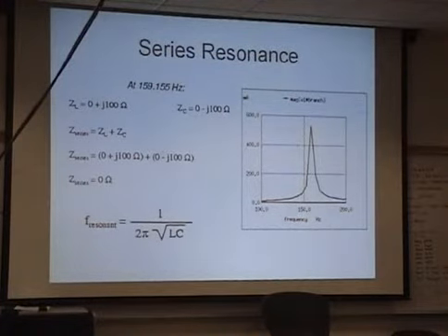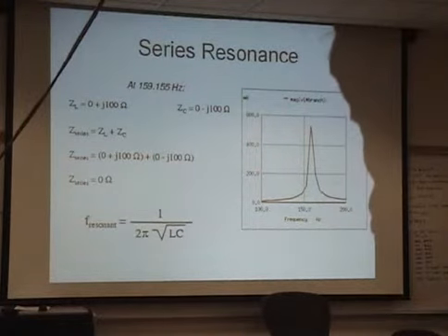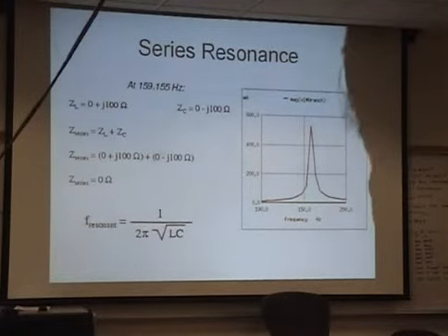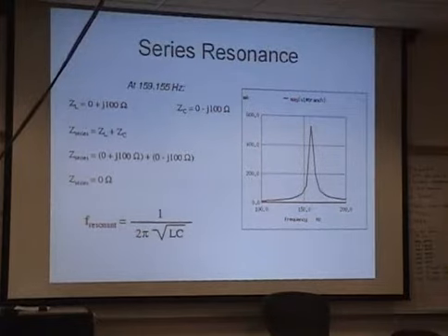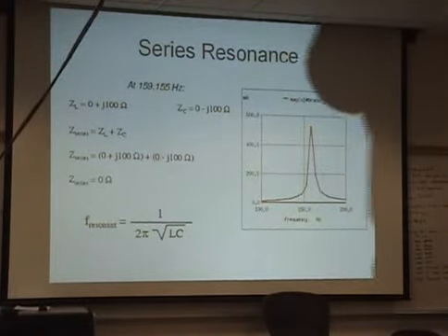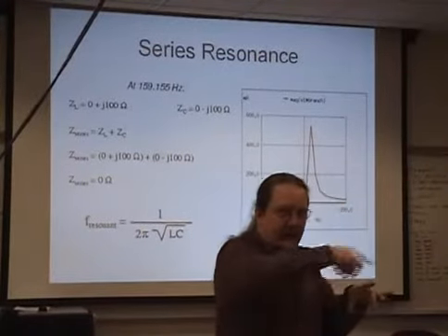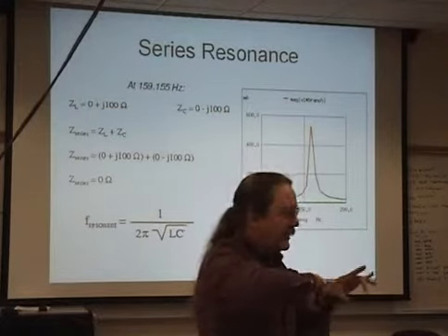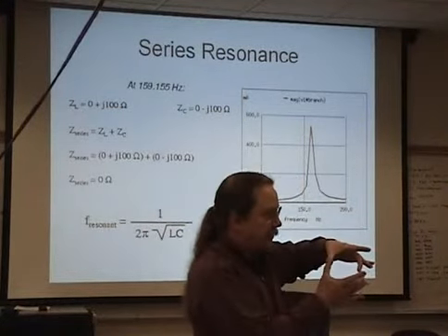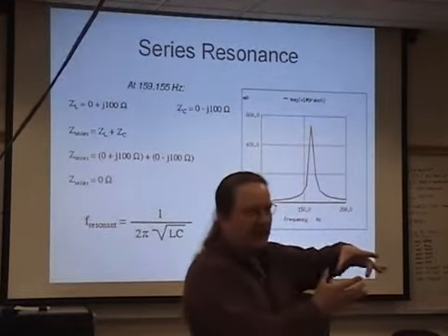Here are some example radiation patterns. The one on the right is your quarter wave vertical. So you'll notice if you turn that upside down, all of a sudden your lobes are going to be pointing down. So if you're higher than your compatriot you're trying to converse with, you'll be pointing down at them with your lobe. Their antenna is going to be pointing up at you, and you'll have great contact.